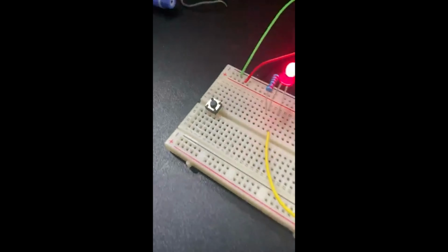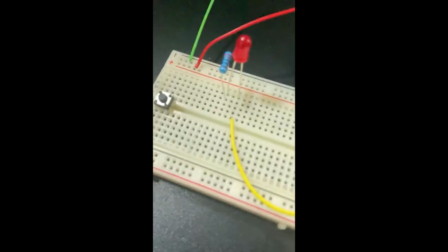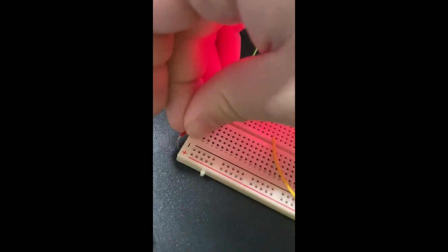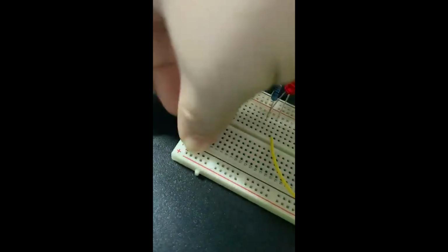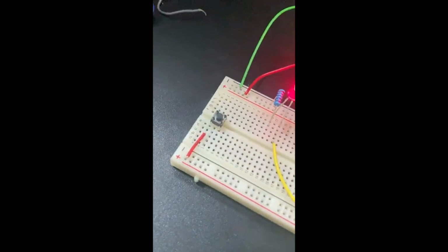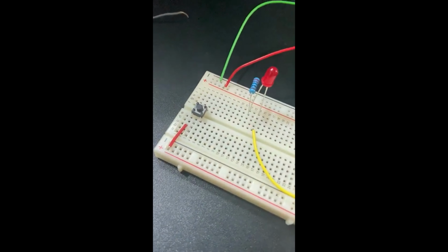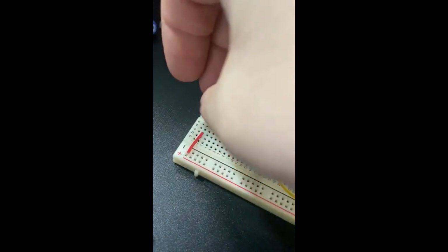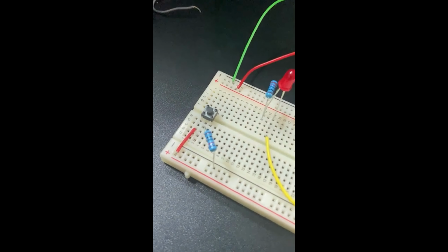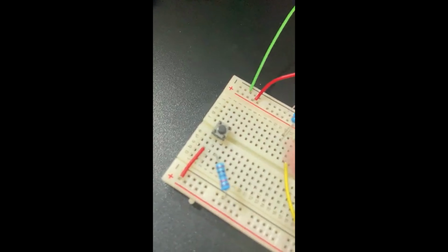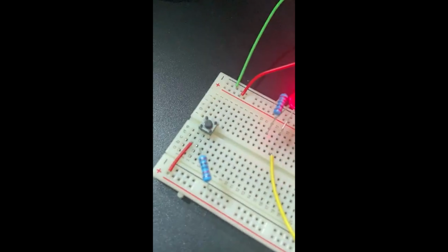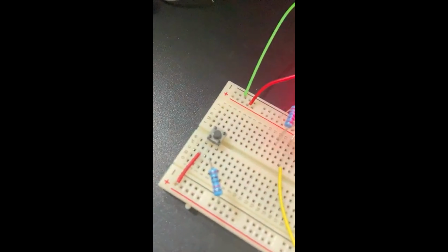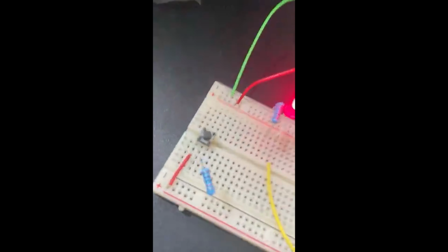So in order to connect this up, we're going to connect one side of the button to power, just like this. Boom. And then on that same side, we're going to connect this 10,000 ohm resistor to ground. I'm just going to plug it in like that. Because there's a lot of resistance on there, the electricity is not going to flow to ground. We'll be able to tell that the sensor is happening whenever we press the button, because there's this big resistor on the grounding.